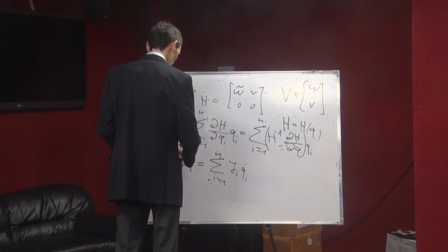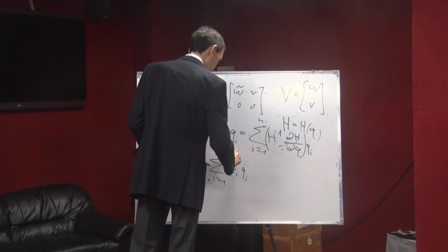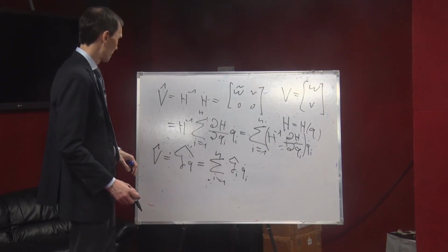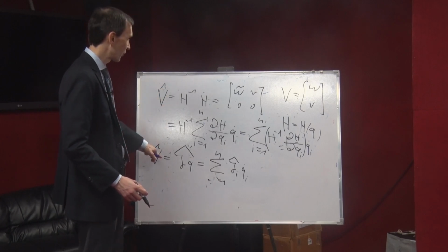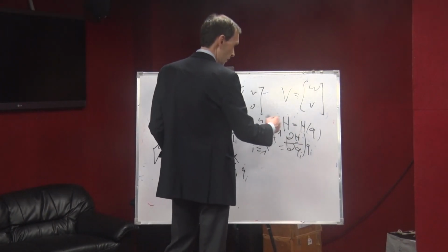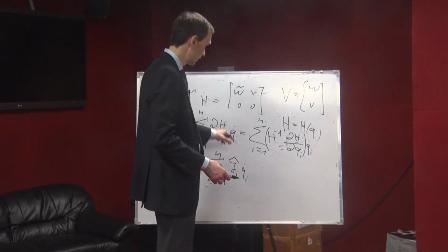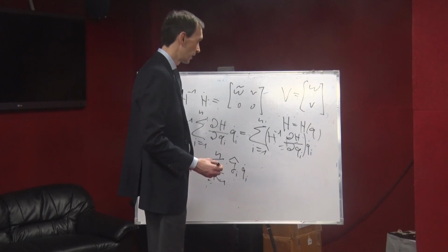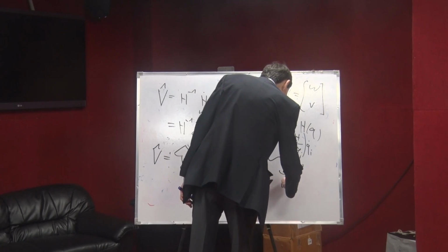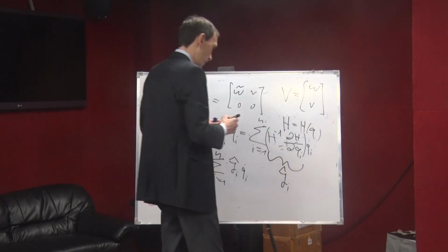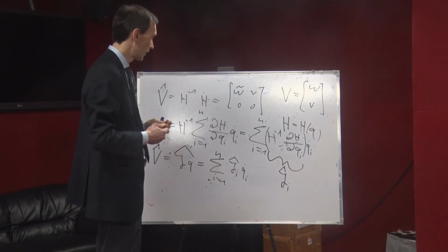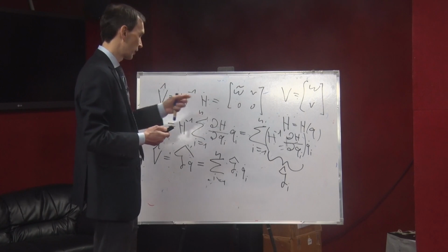So essentially, apparently they must be the same, right? That means the ith partial is essentially the ith column of J, saying that this is nothing but the Ji hat, the instantaneous screw coordinate of joint i.